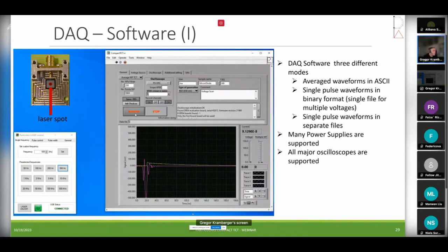So now it goes to 0. What you actually see is a flat line, right? So no signal because there is no field. And then as soon as you start biasing the sample, you see the signal increases. Now at 20, it's already depleted, and you can see that the drift ends here. It's not exponential anymore. And then the higher the bias goes, the higher the current and shorter the signal.